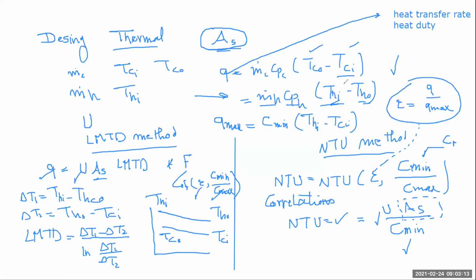I can do it here in Dhahran. I can do it in Riyadh because it hardly reaches freezing temperature. But for areas where you can expect the temperature to go below freezing, then you may use a coolant similar to what you have in your car, an ethylene glycol solution. Why? Because its freezing temperature is much lower than zero, maybe minus 27, minus 30, or whatever. So even when it snows, when it is freezing, it still remains a liquid. So it still circulates in the pipes.